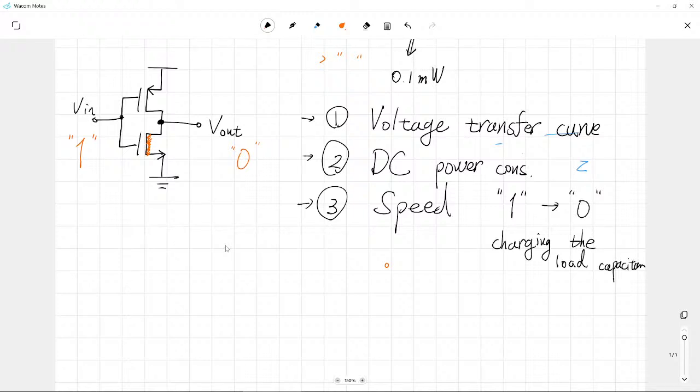And think about our PMOSFET here. Yes, here we have VDD, and the gate voltage VG is also VDD. So then what is the VGS of your PMOSFET? Then VDD minus VDD.